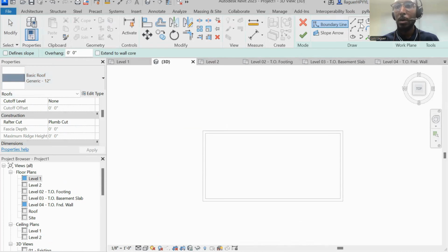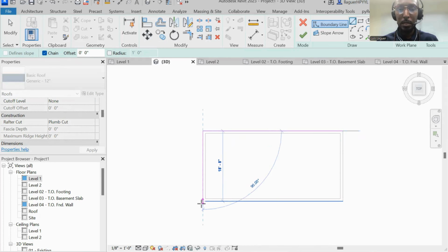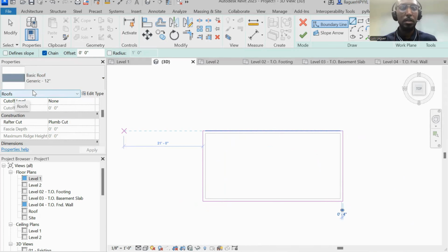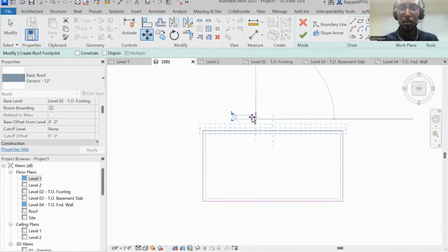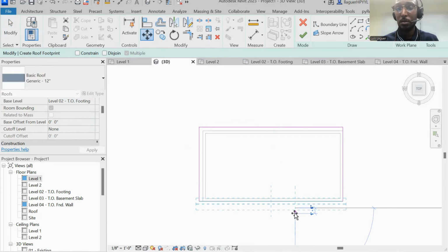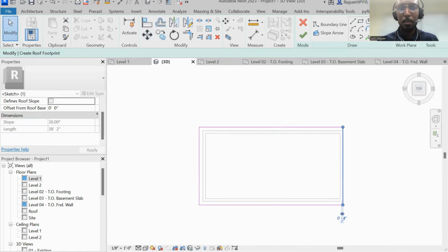So let's go. We have an option again. We can place with our lines, and you can use the lines or the rectangle tool, depending on the shape. But let's do the lines. Let's go from endpoint to endpoint, right? Each one of these endpoints is going to be lined up with the roof. And remember, roofs usually have an overhang. So let's say I wanted this overhang to be a foot off the edge of the wall. I'm going to move these over 1 foot, just for the sake of simplicity. There are many different ways of doing this, but we'll just keep it simple. 1 foot. Okay, 1 foot. I'm going to click our check mark to confirm.